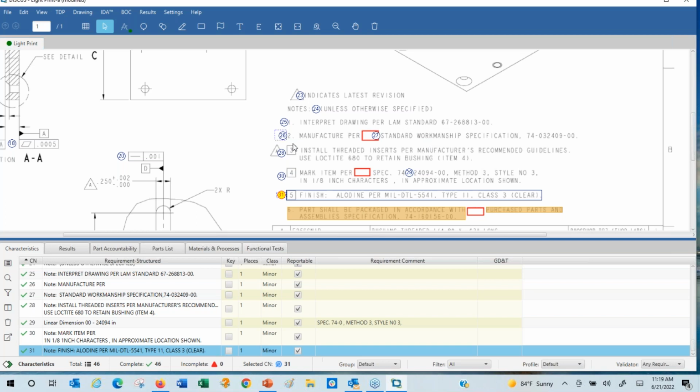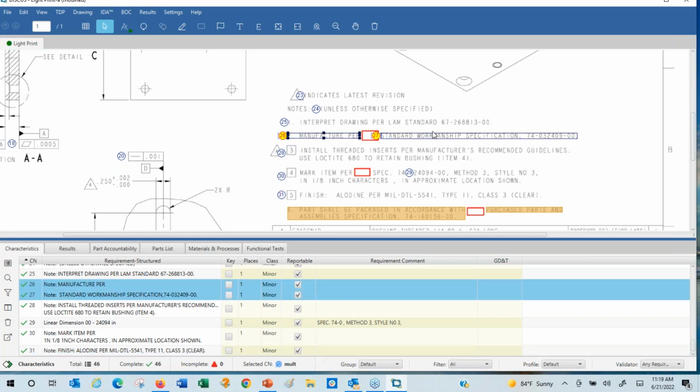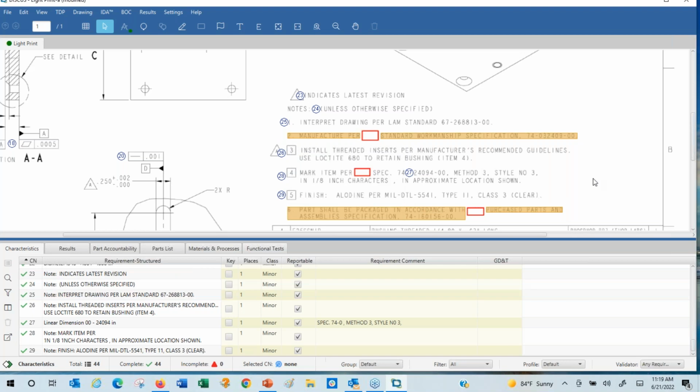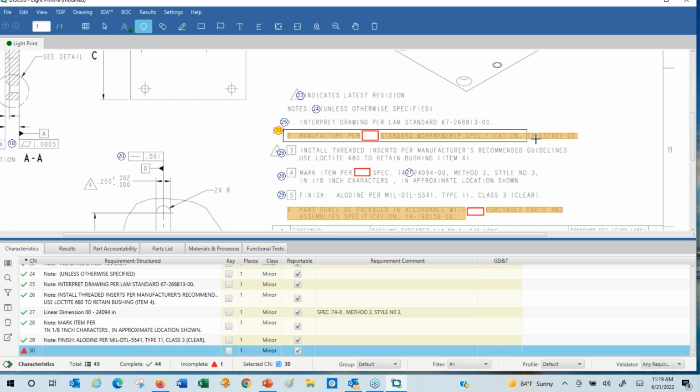I'm going to show you another way how to manually balloon. I'm going to manually balloon this one because sometimes notes can be a little sticky wicket and the auto ballooning may not work for you, but it usually does pretty well with notes. If not, get your balloon icon, press your shift key. Okay, I have it pressed down and I drag a rectangle around the whole thing. See that? Wait for it. I don't have to shift from notes to that anymore.